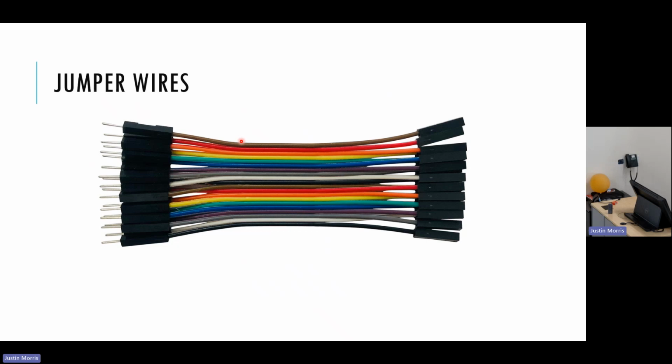Yeah. For the colors, does it matter which one? Like, say I want to plug a black one, but it says I have to plug a blue one in. Will it not work, or it'll just? They're all the same. Okay. It's purely for information purposes. Having a standard of, if it's black, I'm connecting them to ground. But if you wanted to connect a red wire to ground, that would still work. They're all just for making connections. The color is just to help you differentiate them, especially when you get into larger projects.